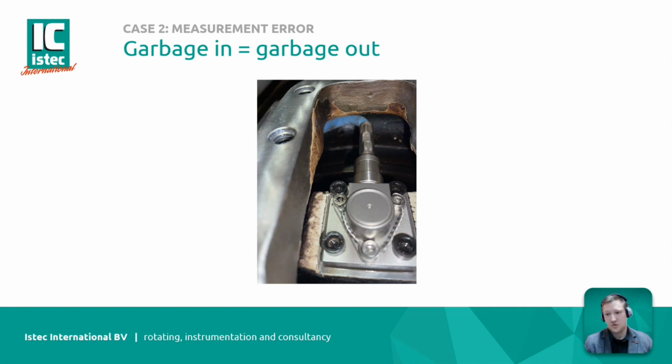When a cable gets in contact with the casing and there is a contact between the wires and the casing, you can get ground issues. And they can cause the same kind of pattern of the vibration. And it's a completely different problem to solve.